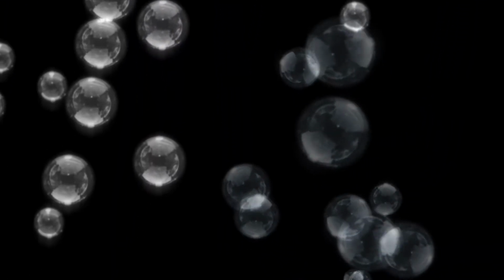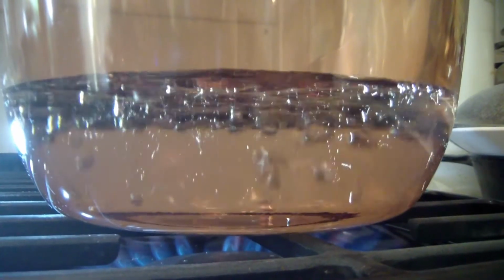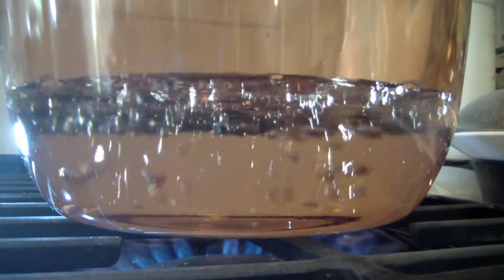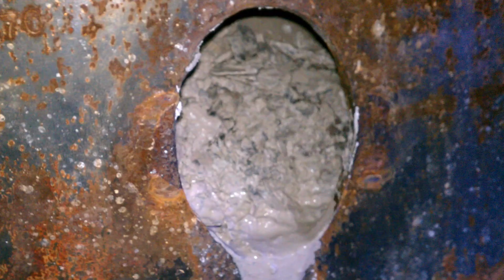It's these hidden particles that become problematic for a steam boiler. It's not until a boiler is open for inspection after hours of operation that the particles' effect becomes evident. The bare metal of the boiler's interior has developed a white, plaster-like coating. In the bottom of the vessel is a thick mud.